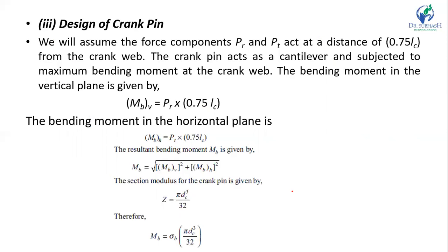So we will assume the force components PR and PT act at a distance of 0.75 LC from the crank web.